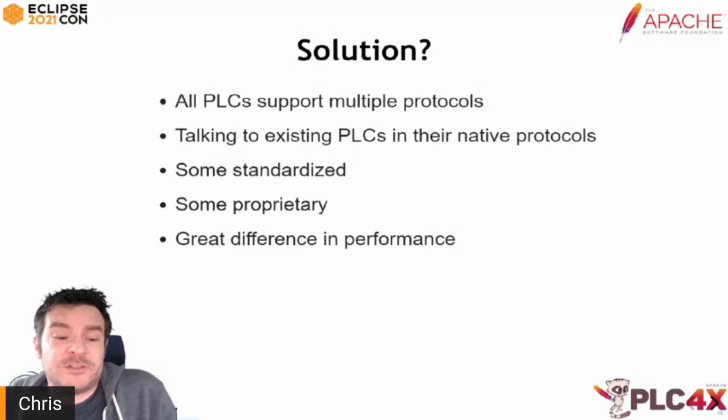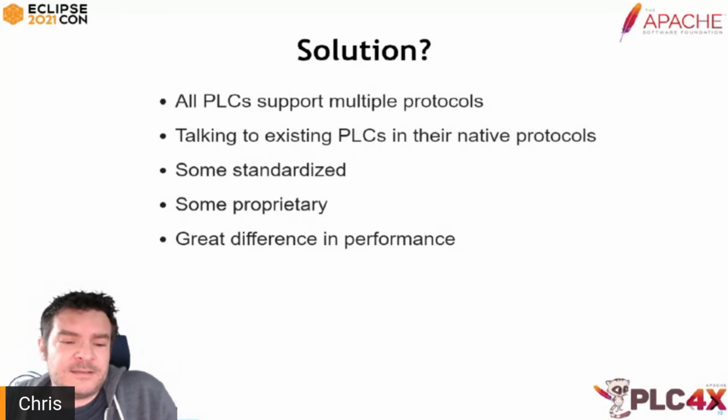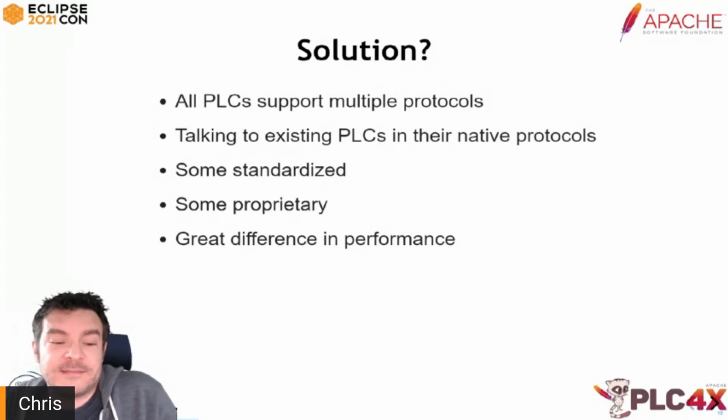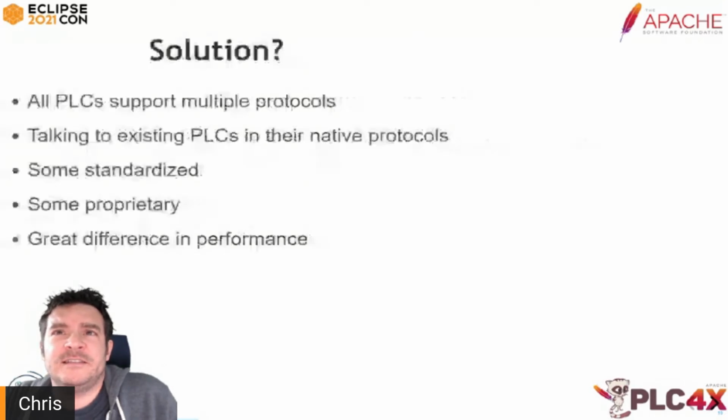Maybe just as an example, as I mentioned with OPC-UA. With OPC-UA on one of the really big fat Siemens S7-400 devices, we were able to get 200 data points out every 2 seconds. If we wanted more, the system just shut down because it was completely overloaded with I/O. As a comparison, getting 2,600 data points out of an S7-400, the same device, every 200 milliseconds using the S7 protocol wasn't any problem at all. You couldn't even really see a big impact on the I/O. So just because you can reach a system, it doesn't mean it's also the ideal version.